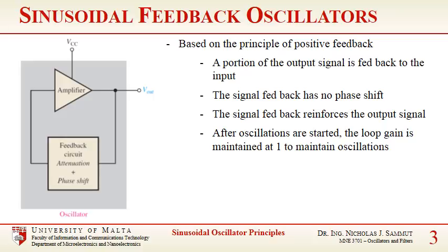In fact, you can see this in the diagram on the left, where the output is being fed back through an attenuation and phase shift circuit and fed back into the amplifier input. We see that the signal has no phase shift when it is fed back, and the signal that is fed back reinforces the output signal. So in this case, it is known as positive feedback, not negative feedback.